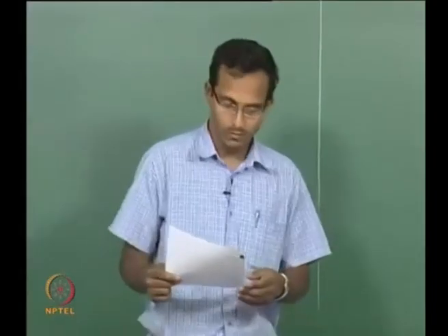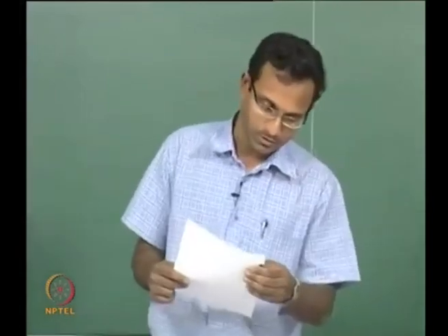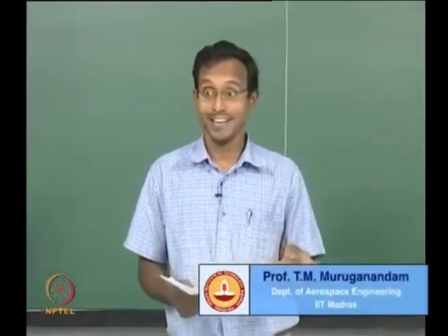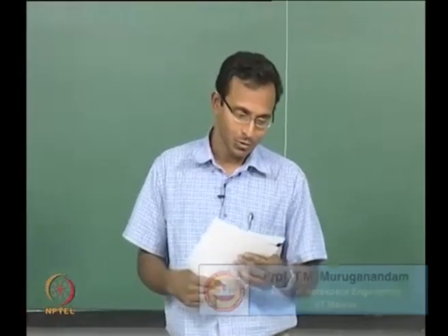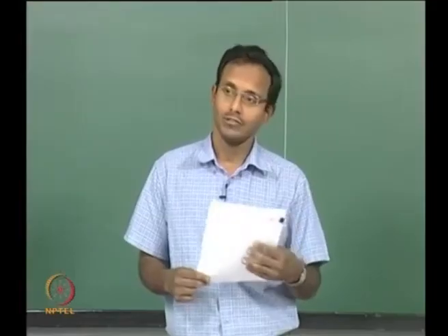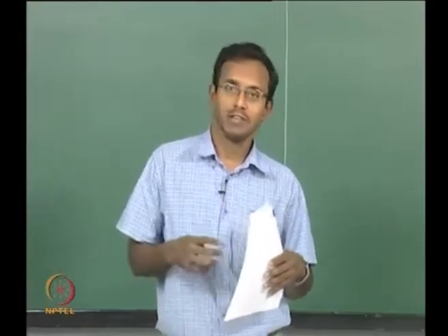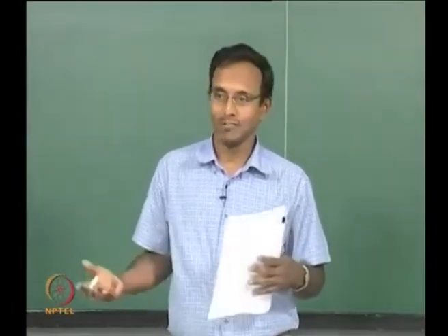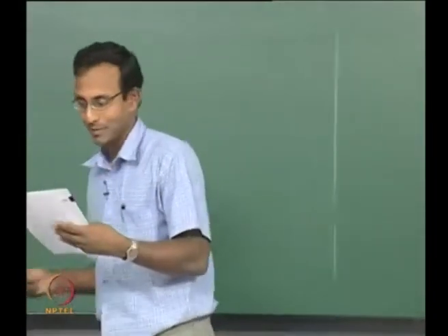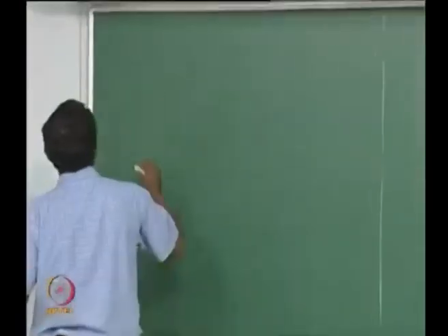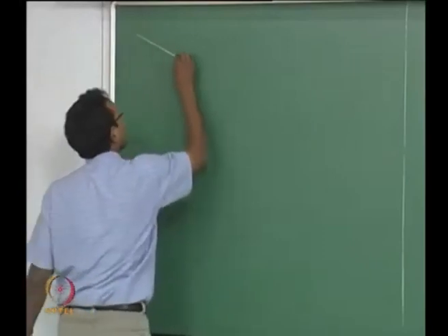Hello everyone, welcome back. We started going through the procedure of how to solve a problem in gas dynamics, 1D isentropic gas dynamics through a convergent divergent nozzle. I discussed how to solve when it is a simple case of isentropic subsonic flow fully. I don't want to go through that. I believe you can solve it by yourself. All you need to do is A by A star calculations. Now a better one to do will be a case where it is non-isentropic somewhere in the middle.